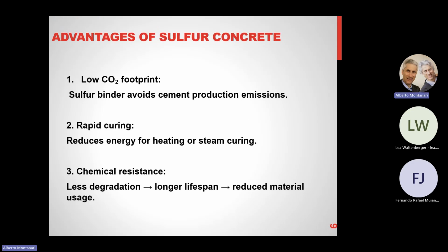And the advantages of sulfur concrete: low CO2 footprint, because the sulfur binder avoids any cement production emissions, and rapid curing, which reduces energy for heating or steam curing in cold weather when we construct concrete buildings. And the last one is chemical resistance. Because of this, less degradation, longer lifespan, and finally reduced material usage.